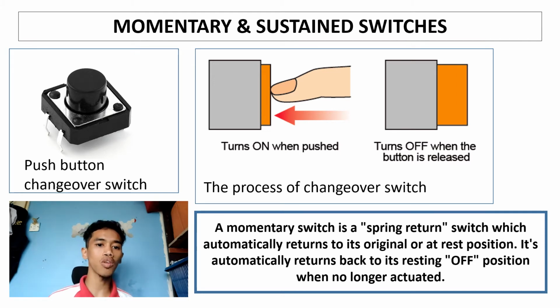One of the main reasons for choosing a momentary switch is operator safety. If it is not safe to leave the device on, then it is safer for an operator to have to compress the switch so that the device cannot be left unattended. Momentary switches are used on heavy-duty roller doors. The operator must hold down the switch when the door is opening or closing. If there is any obstruction in the doorway, the operator can quickly stop the door from closing, preventing an accident.